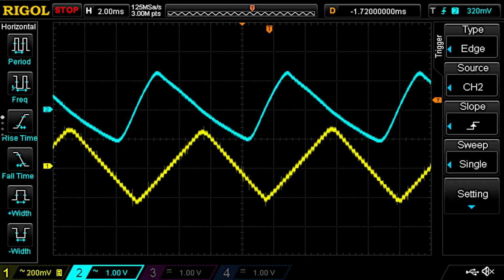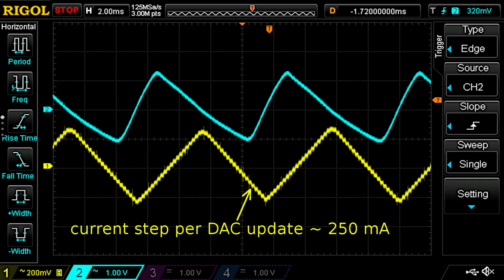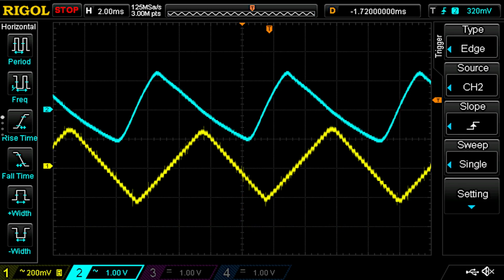I have a little over 2 volts of 120 cycle ripple. At the same time, I've got about 5 amps of current ripple. The update routine is running at around 5 kilohertz, so that's about 41 updates per one cycle of the ripple. And you can actually see the steps in the current waveform. Here at the current peak, you can see that it is just barely affecting the voltage ramp. I think that tells me the caps in the power supply are still in very good shape.